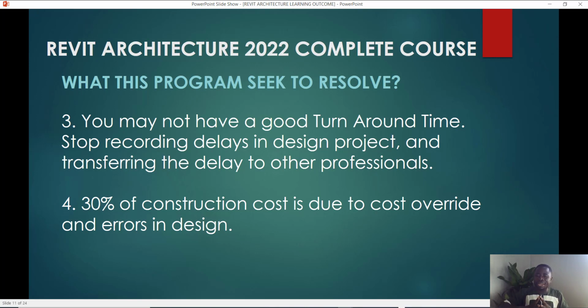So the drawing is done in CAD and given to the structural engineer. The structural engineer designs the various sections of the columns and the beams, and when they finish, you pick the same plan and give it to the mechanical, electrical, and plumbing specialists. Now, the challenge here is that there's no proper coordination. When they finish their work and you want to do a design review, you put them together, and you see that yes, it may work in that 2-dimensional space. But what of the depth? What of the third dimension? That is where you start having a lot of problems on site.